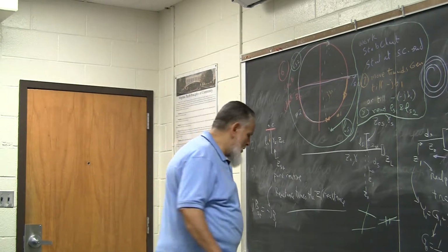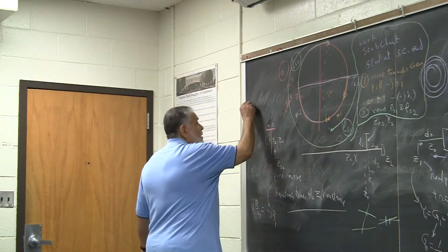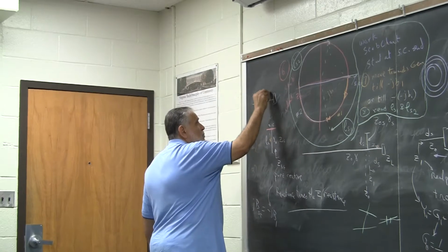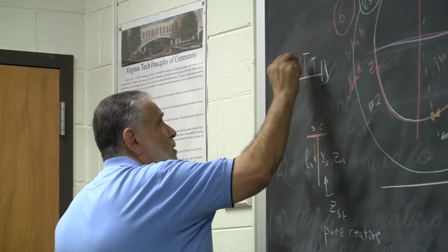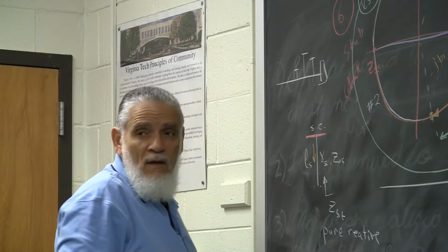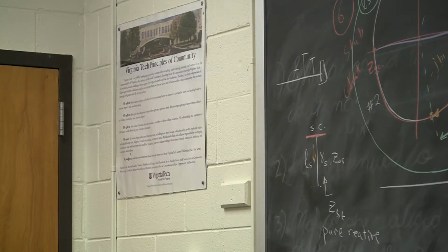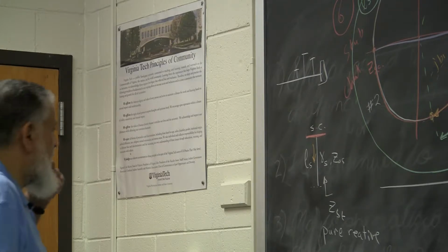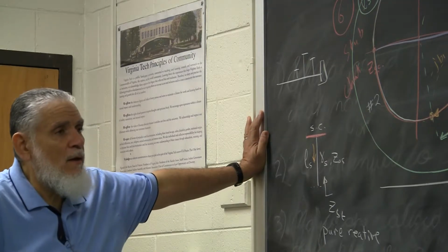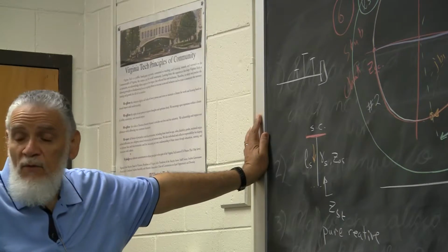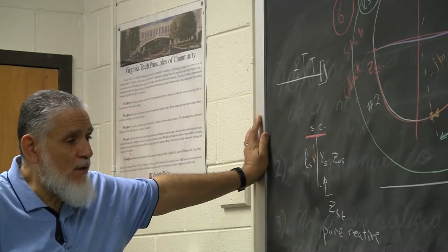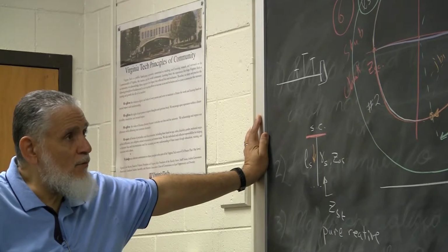Right? 3 stubs on a line can guarantee that you match any impedance that you care to have. Right? And that's an exercise that we usually assign as homework, but I'm not going to do that this time because we're kind of behind. I don't want to get consumed in that. But it's something interesting for you to investigate. So go to your references and check them out.